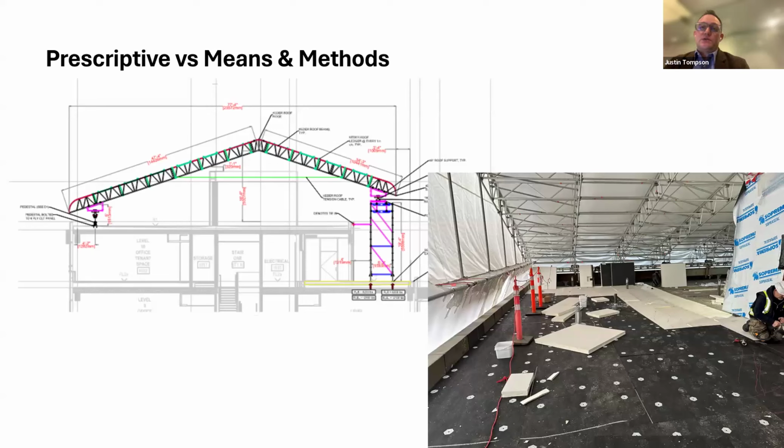And then it also evolved as they got up to the roof. One of the lessons learned I think we took away from this is, in the mass timber protection plan specification, there was a lot that we left to means and methods of the contractor. Looking back, we would change one word in almost that entire spec. We would change "may" to "shall," and actually make it prescriptive so that the price is absolutely built in, and leave fewer things discretionary to the contractor.